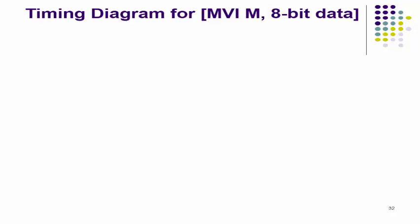Next example, that is MVI M, 8-bit immediate data. So MVI M indicates move immediate 8-bit data in the memory. Here M means memory, or M means HL pointed content. So the operation of this instruction you know very well. The 8-bit data which is available in the operand field gets copied into the memory pointed to by the HL register pair. So the HL register pair is nothing but memory.